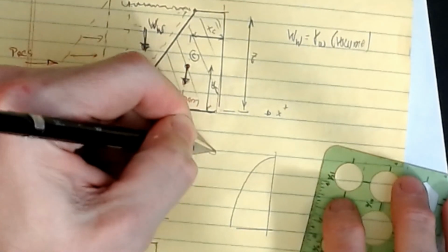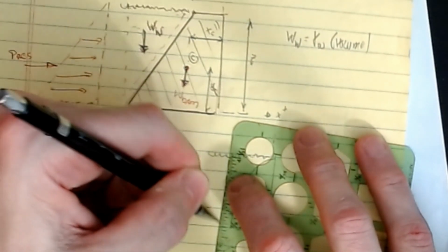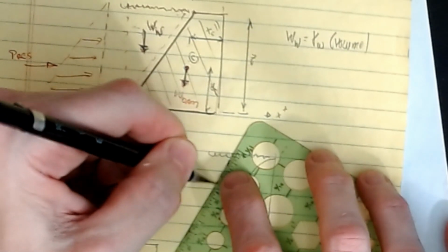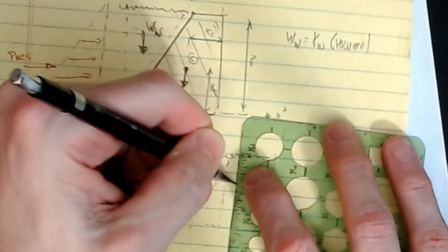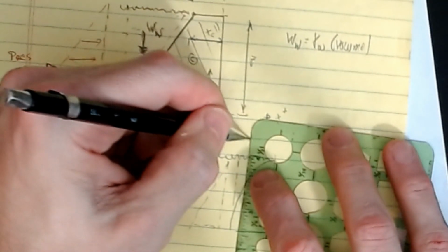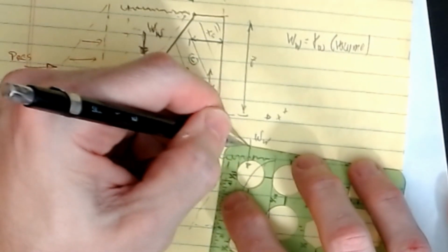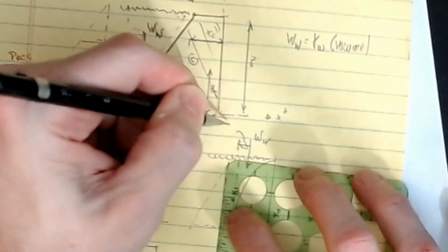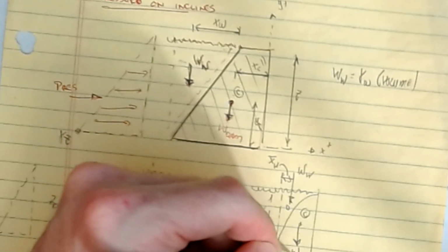Okay, I come in, here's my water elevation. Okay, my pressure then does this, associated with it, and then we do have this sliver of a weight that results in some weight of water here, and then that has some dimension, if I want to call that x bar W, would be a way to do it. And then once you have that point located, again, that's a C, and you still have the weight of your dam, which is located at its C location. Here's my weight of my dam.